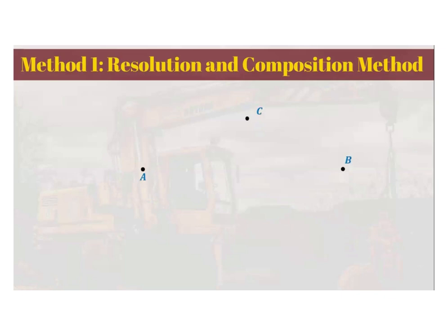What if you have 3 points? So in the same way, we're still going to resolve them into components. So say for example, you have this linkage wherein the velocity of A is known as well as its direction. So for B, again, you are going to resolve A into components.